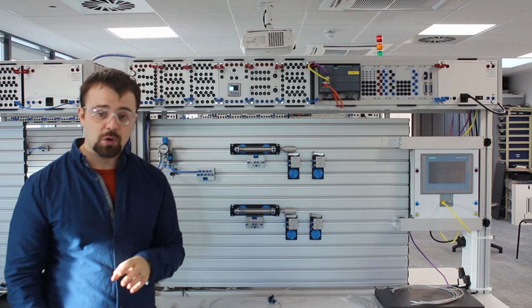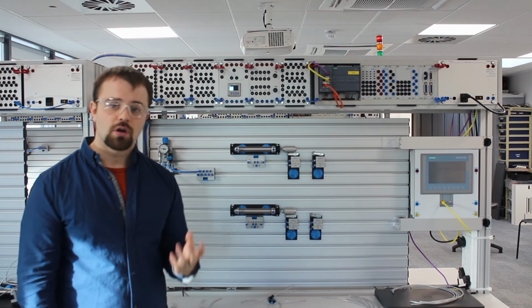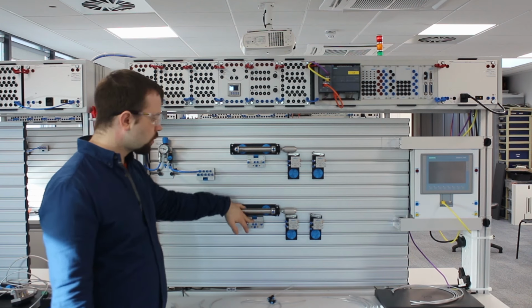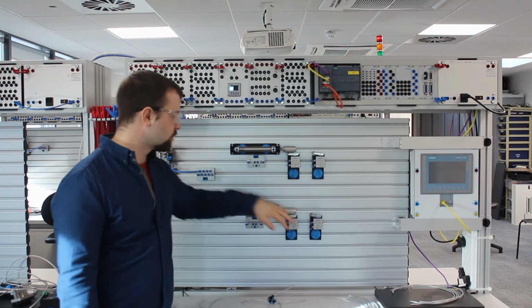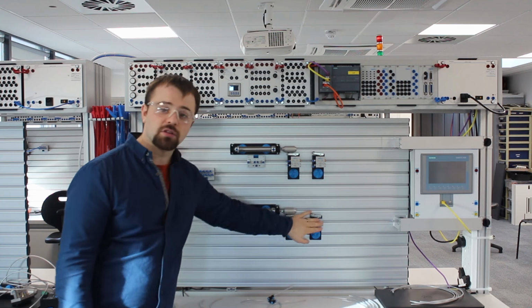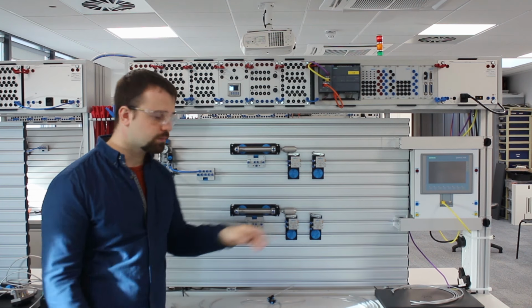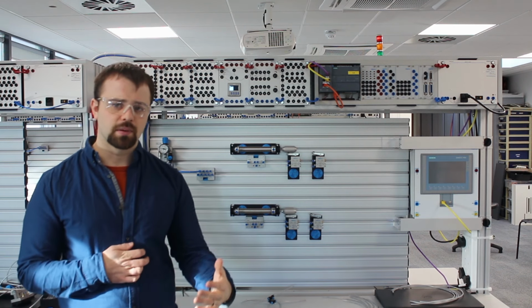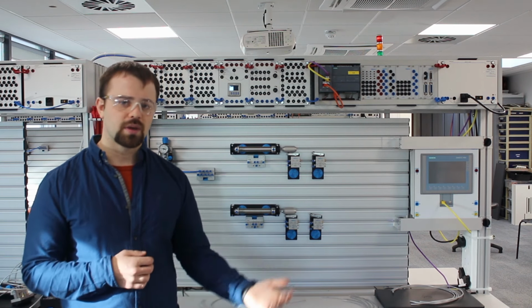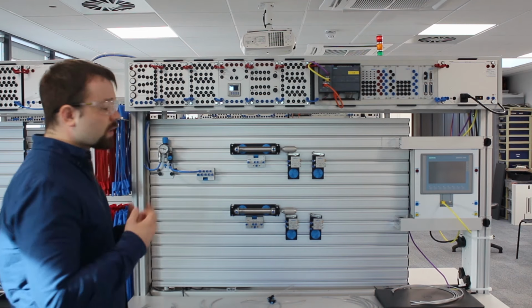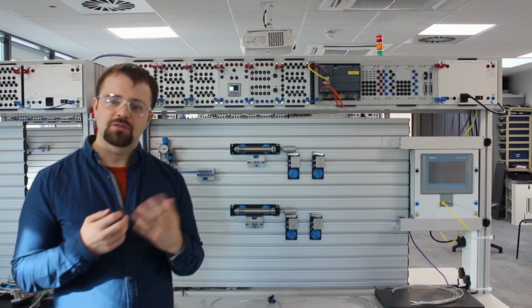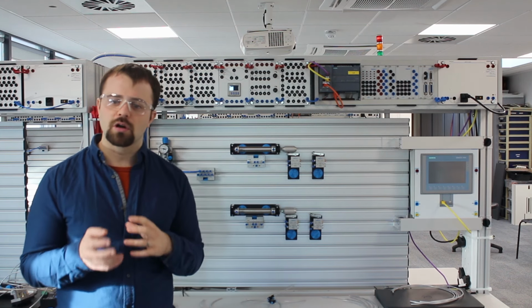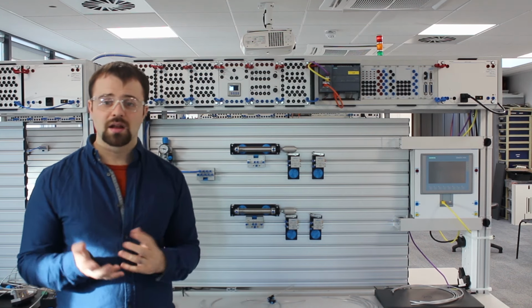In this case, the same ones we were using in the previous example, 5-port two-way valves, one on each. I've also fitted roller switches to my cylinders, so one for each position that it is possible for them to be in. So the sequence we have is A plus, B plus, A minus, B minus. So you would think that the first thing you would do is try and get the first bit to work, the A plus, but in reality it's often better to work on it second. But we'll come to that in a bit.